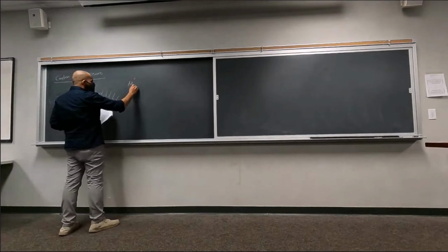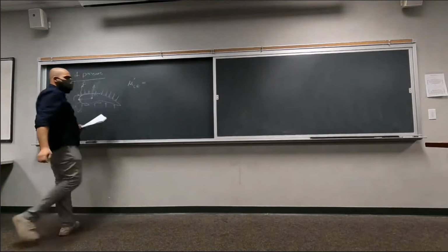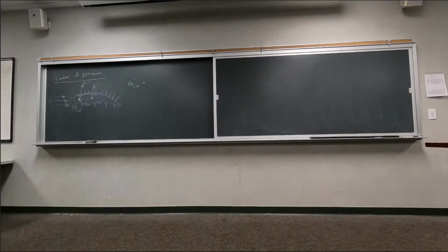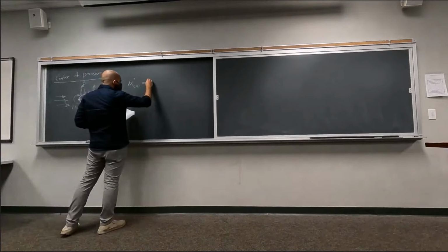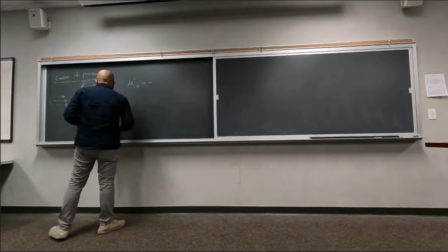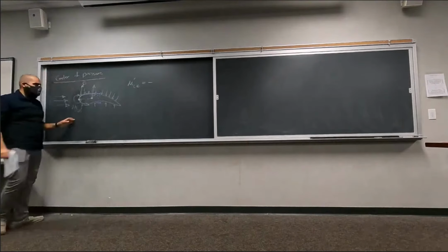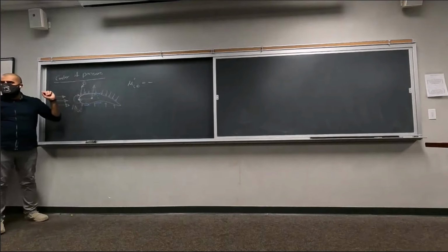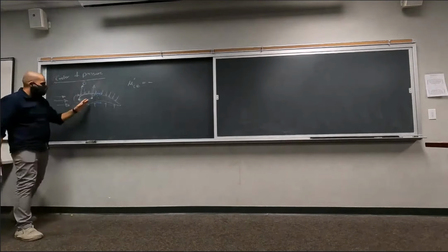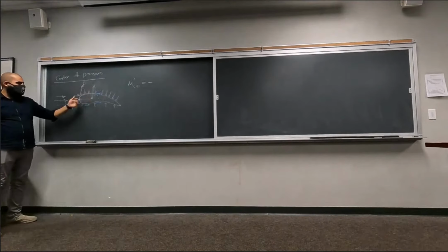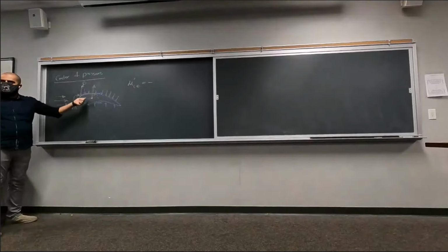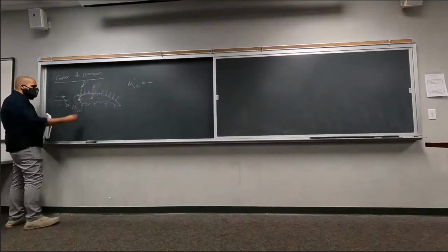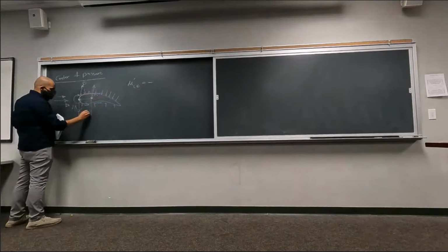So based on this, the moment at the leading edge, and we are looking at a two-dimensional body, so this is M prime, has to be equal to the negative moment that is being applied by the force at this point. Okay? How can we calculate the moment that is being applied to the leading edge by this force? It's the force multiplied by the distance, right? Let's call that distance x.